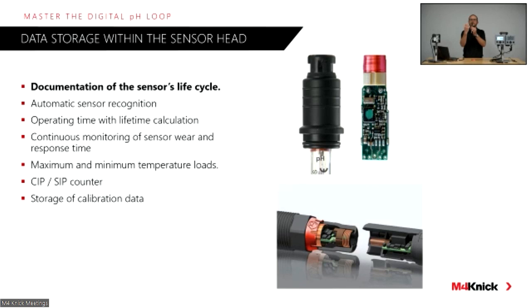a microprocessor inside it. And the number one priority of that microprocessor is to take that analog signal, that voltage, and convert it to a digital signal to allow the ones and zeros to be carried from the sensing element to the transmitter. And most often that's done on standard industrial digital protocols such as RS-485.